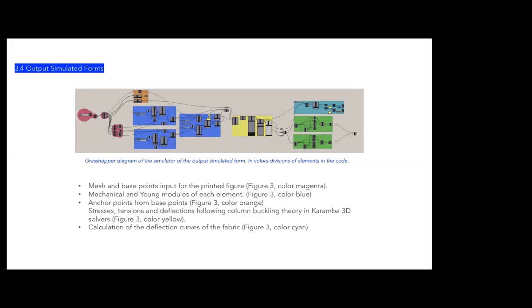Based on initial prototypes, it was observed that there are mainly 3 types of Lycra bonds: fixed, hinge, and free, since their mechanical behavior was relatable to the column buckling theory. This combination will generate a deformation in the simulator. Considering that the pivot type support generates parallel and perpendicular reactions, the fixed support generates the same reactions as the pivot one, added to moment of torsion reactions towards the center of the bar. The free support generates reactions only on the axis towards which an external force is applied.